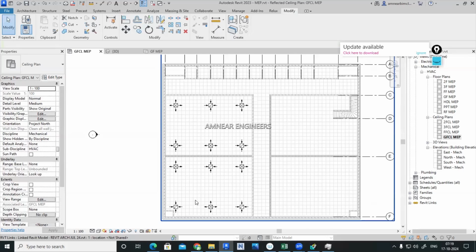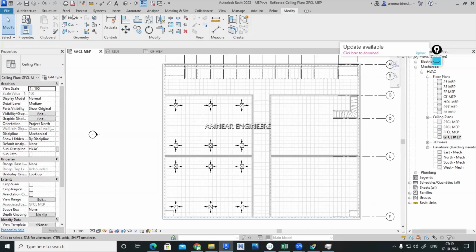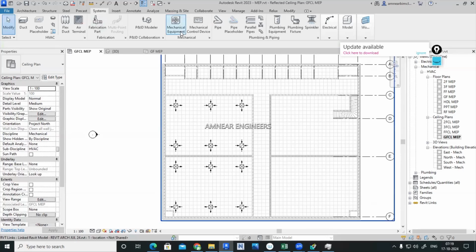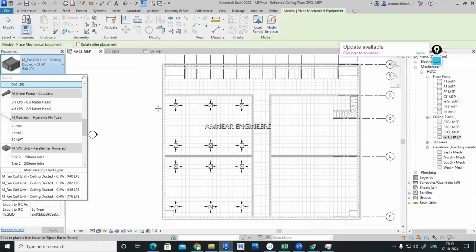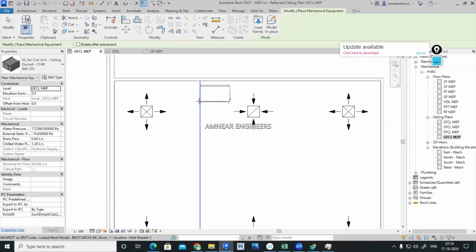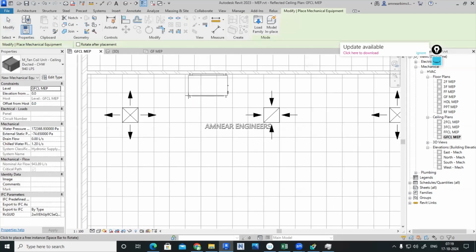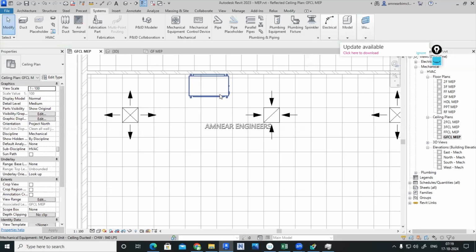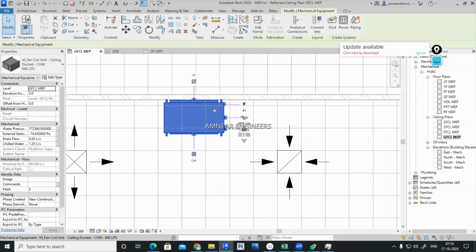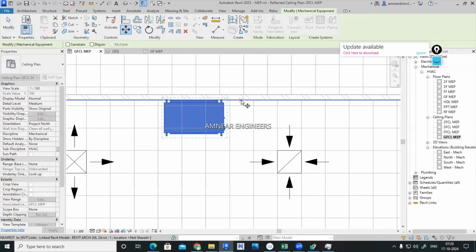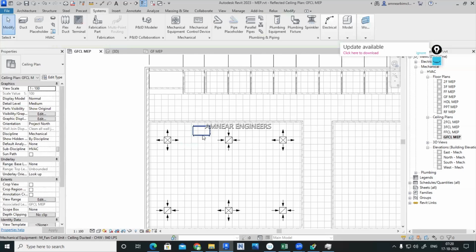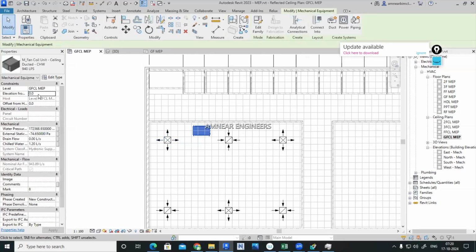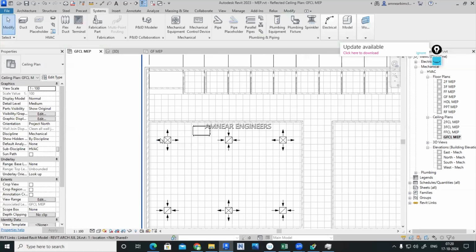And after that, I'll be doing the manual routing. Just go to the systems, mechanical equipment. This. Okay. So I'll be placing somewhere here near to the wall. You know, it is taking the return from the backside only, since it is an open return. Minimum distance from the obstruction 300 mm. So move it towards 300. And from the ground floor ceiling level, the tentative elevation, means from the reference level to the bottom of machine, I am providing 500. Elevation from the reference level, it is 500 only.